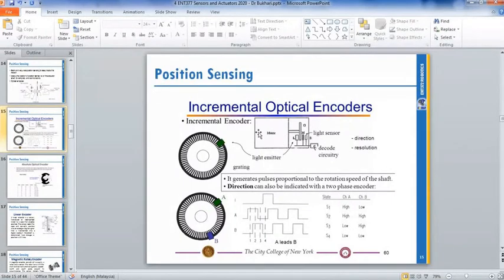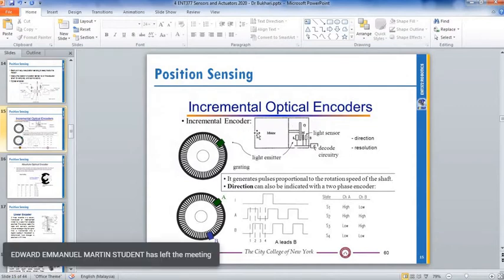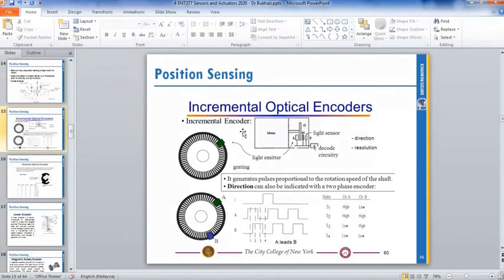So this is the motor, and you put the encoder here. Normally a motor that has an encoder has a shaft at the front and the back. At the back side they put the encoder, and the shaft at the front side you connect to your tire or to your robotic arm. The back side you connect to your encoder circuit.